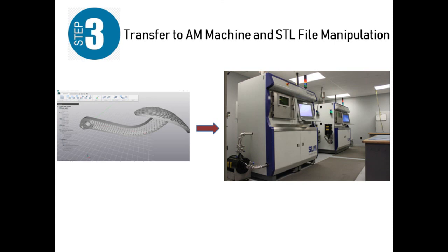Additive manufacturing system software normally has a visualization tool that allows the user to view and manipulate the part. It is quite common to build more than one part in an AM machine at a time. This may be multiples of the same part, thus requiring a copy function, or completely different STL files. STL files can be linearly scaled quite easily. Some applications may require the AM part to be slightly larger or slightly smaller than the original to account for process shrinkage or coatings, and so scaling may be required prior to building.